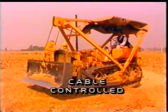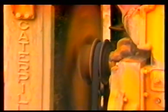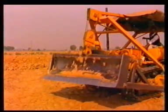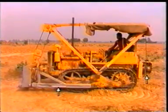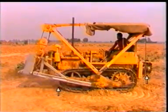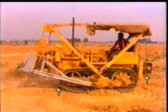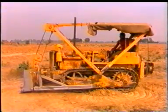In a cable-controlled bulldozer, a hoist is mounted on radiator guards, and push arms are hinged to brackets bolted outside and to the bottom of blade. The blade is raised or lowered by means of a cable on hoist drum.